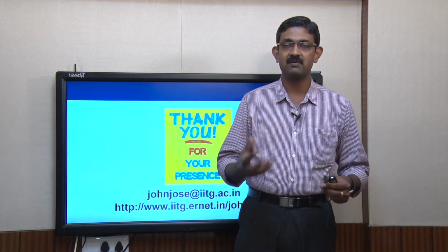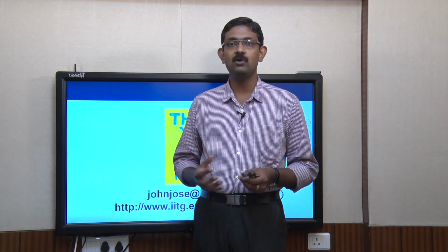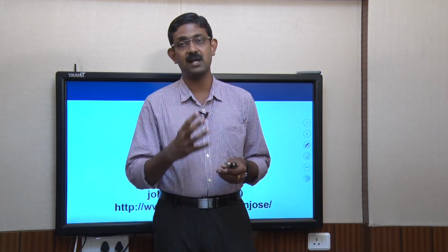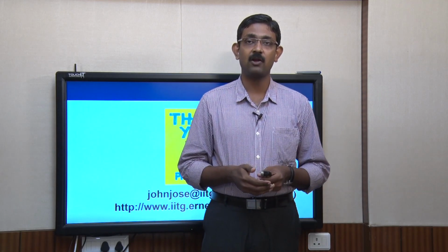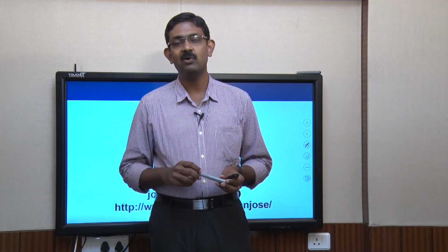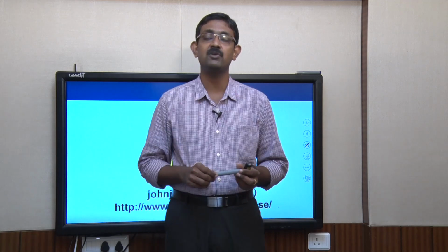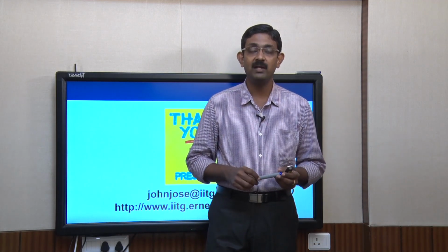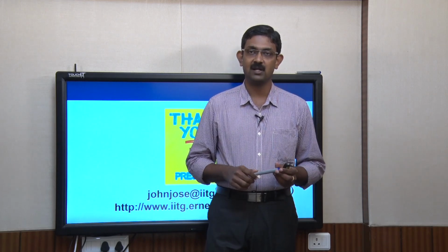So, in the last two lectures, we were trying to understand, can we get rid of input buffers? Yes, we can. We can remove input buffers, but that has to be compensated by an equally good intelligent system that will take care of the flits. In order to reduce the number of deflections, side buffers are introduced. Management of flits to and from the side buffer has to be taken care of by appropriate priority mechanisms. So, in this way, we have learned how buffers can be removed, and there are cost-effective replacements for buffers known as minimally buffered or side buffered deflection routers.